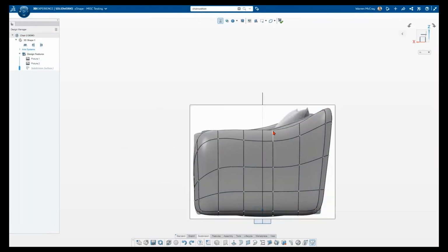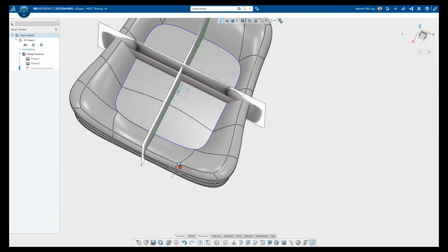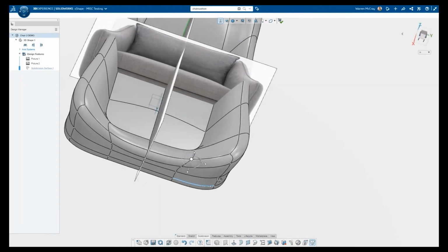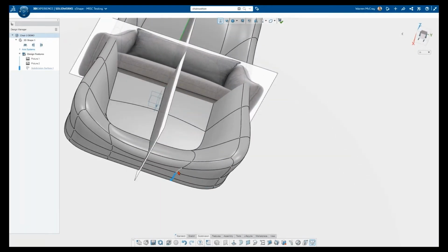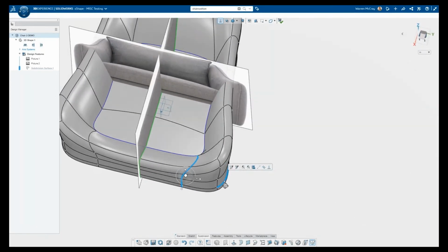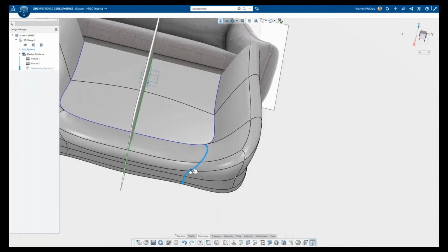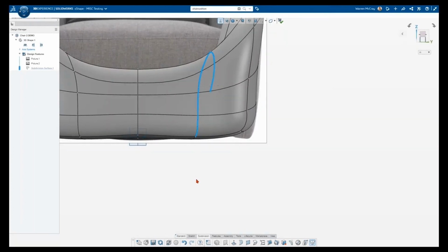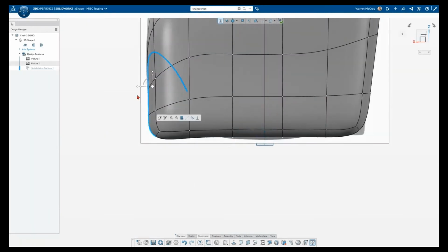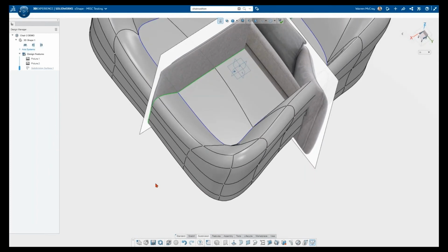So I have to adjust that a little bit more. The side is a little bit irregular, so I'm going to pull it up and straighten it out a little bit. I'm going to keep refining it. So here, what I'm doing, I'm picking individual vertices. You can just pick vertices like that, as well as edges, and just drag them out. Now, the problem here is that it's not subdivided enough. I can't quite separate the right shape from the center of the front because it's just not subdivided enough. I need to somehow split that up.